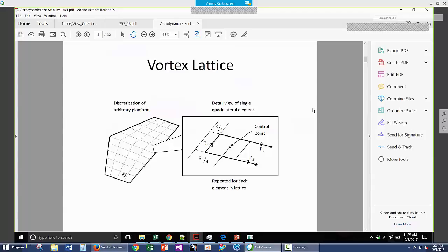We're not accounting for the thickness. So there are thickness effects that can be important, and we're not accounting for those. Things like the fuselage are something that we can accommodate in only very approximate ways. So fortunately, it doesn't impact our actual lift or the stability very much if you have a small fuselage. But those are some limitations here.